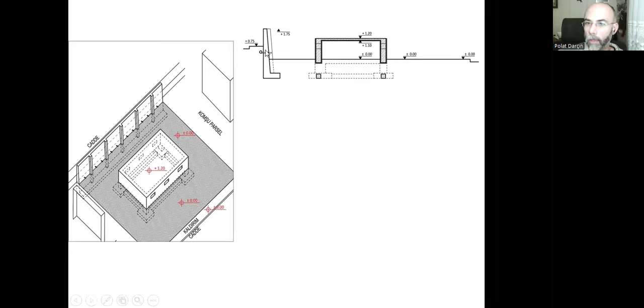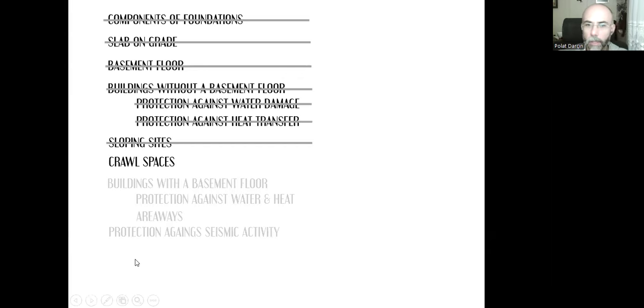Also, it will hold the pressure of this earth, soil, and it will prevent the sidewalk and the road from sliding towards our building there. And if we prefer only concrete, if we don't need reinforcement bars, then we don't need to provide any waterproofing solution because there won't be any steel reinforcement bars to corrode. So that's it. That's a solution that we can do.